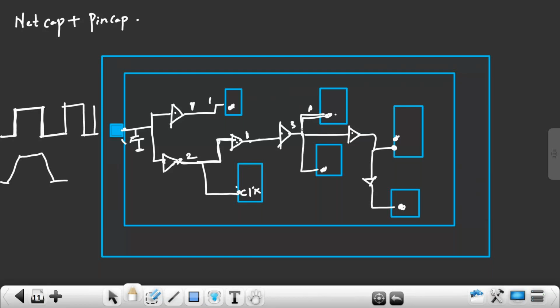3 is a fan out. For this buffer, 1, and this one, this buffer 2 is a fan out. For this buffer, 1 is a fan out. To reduce fan out and to reduce the net length, we build a clock tree like this by inserting buffers. We build a clock tree by inserting what?